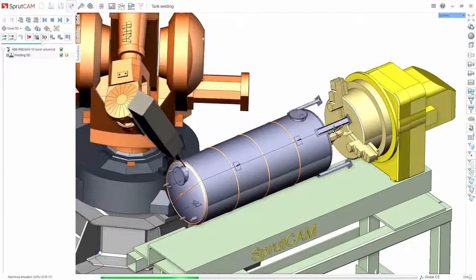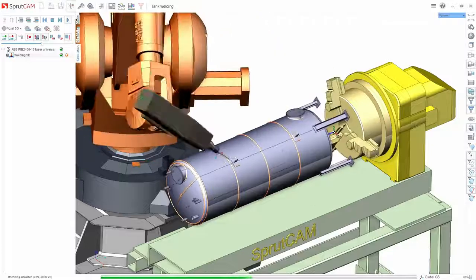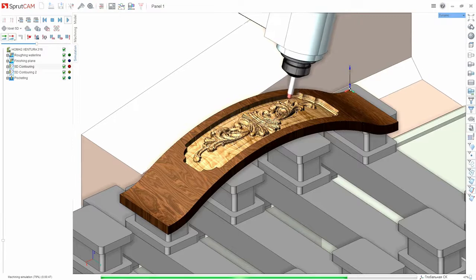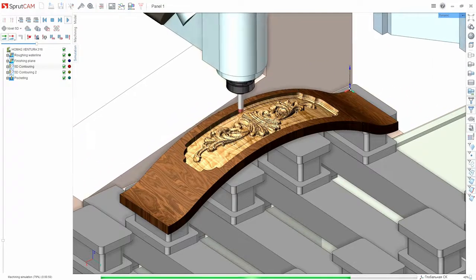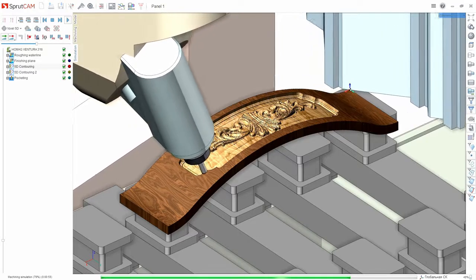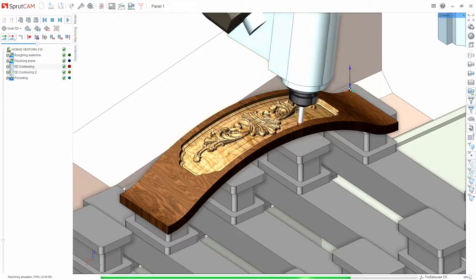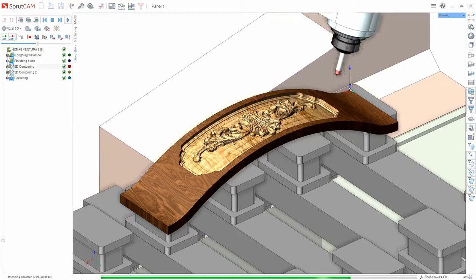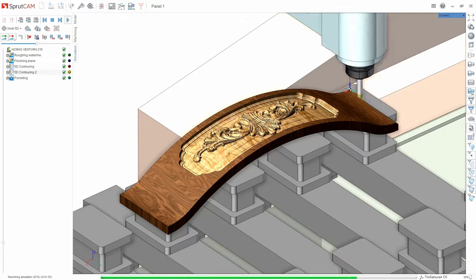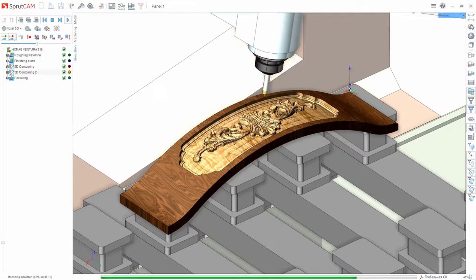And if the first ones work in standard modes, modern machines are often equipped with high-speed spindles which allow high-speed machining, not only removing the metal, but also cladding and then machining it. Modern equipment doesn't always have special software for the NC code generation, and even if it has, the possibilities are limited by the complexity of parts. Older machines in general were not initially packed with special software. Because of this variety of CNC equipment, the need for an integrated workplace arises.